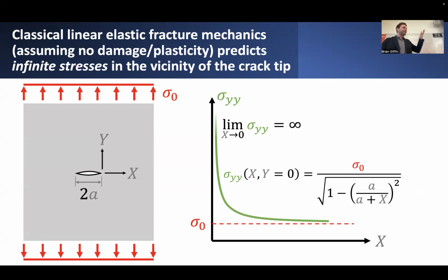And you'll maybe remember from the previous lecture, when we talked about that particular example, that the stress concentration factor, or the ratio of the far-field stress value to the value of stress in the local proximity to the hole in the plate, was roughly a factor of 3 larger than the nominal stress. However, in the case of a crack, where it's not a circle but just a flat line, we can look at what the stress concentration factor is.